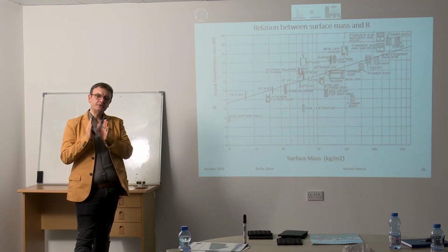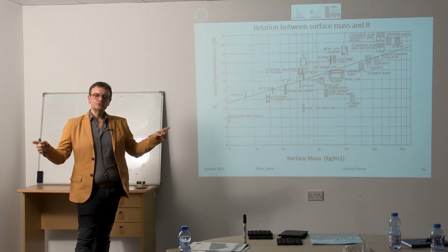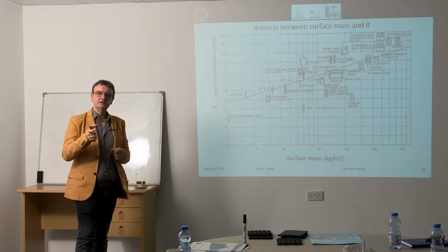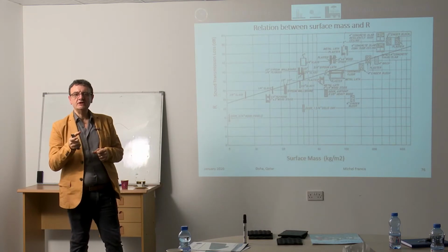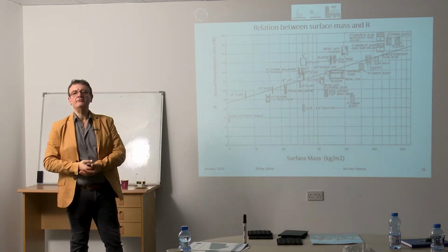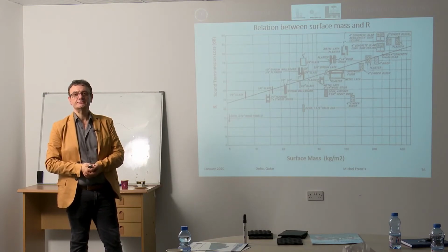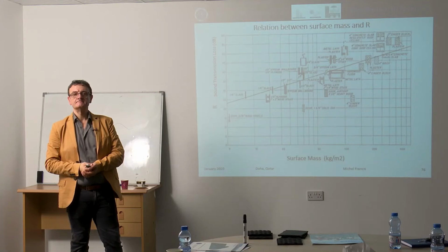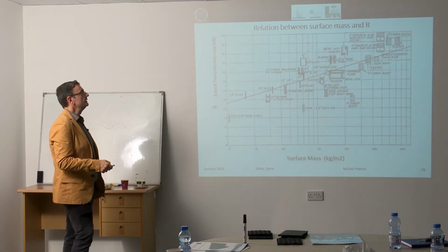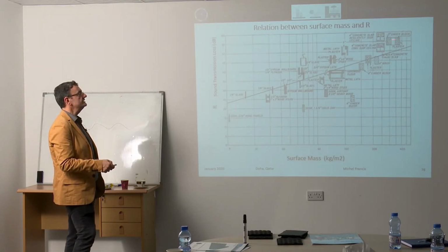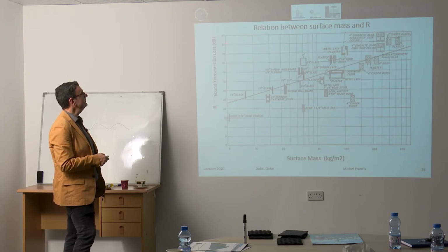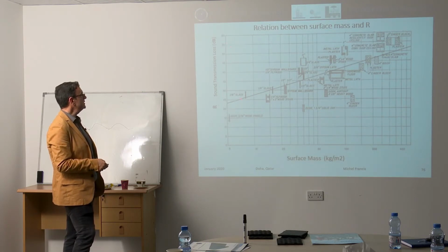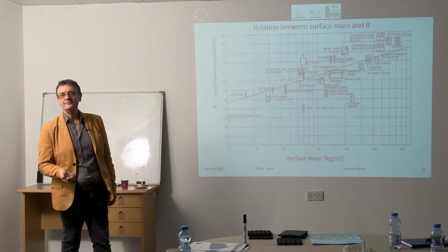We're talking about a partition. So how many square meters do you have of this partition, and what is the density? It doesn't matter how thick it is. What is the density of material per unit area of that surface? That is what is important. Yes, if you increase the thickness, the mass increases. Look here. Obviously this one is the thickest one, and it's going to give you 55, almost 60. This one is very thin, and it's giving you 25. So the thicker it is, the better, obviously.